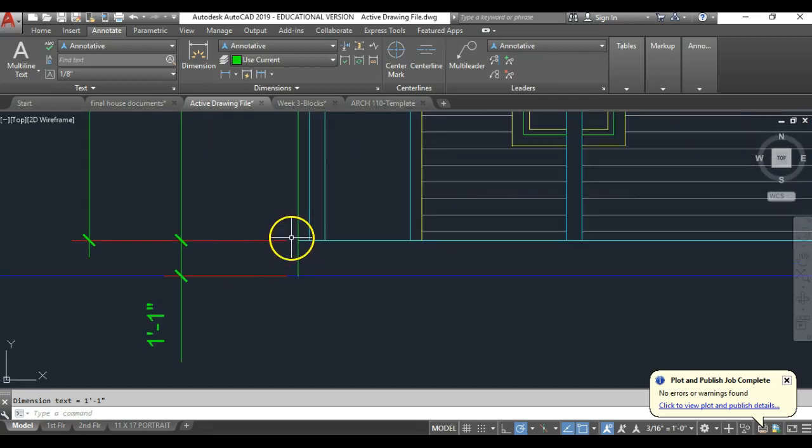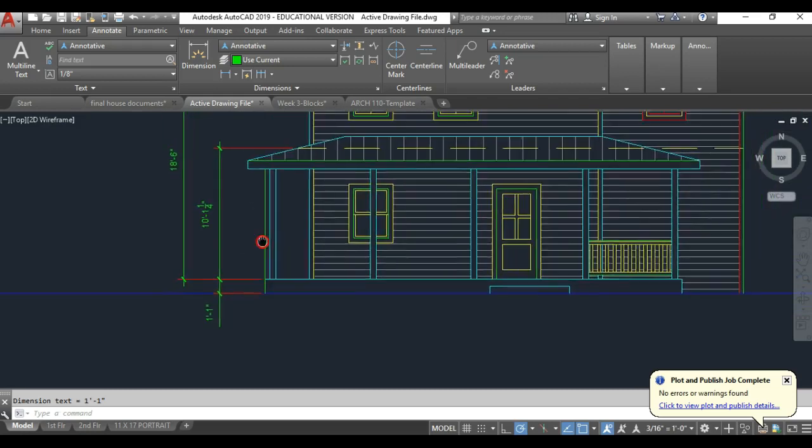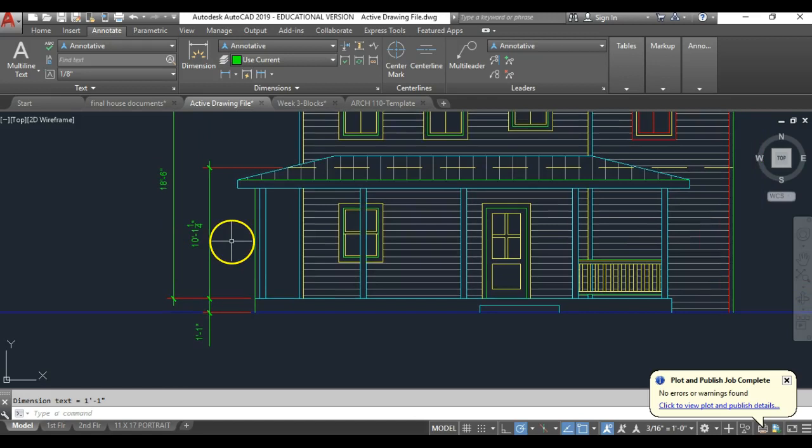Also note, in case you didn't know, there should be a gap between your elements and the dimension line, so that's also correct. So this is looking pretty good, and all the size is going to be correct as long as you have 3/16 of an inch equals a foot. If you haven't done that, make sure to do that. I should have done this before I did any of these notes, although we're using the same file that we've already done this in, so it should be okay. It's just sort of a double check.